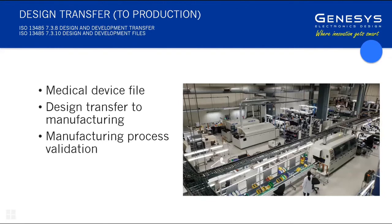So design transfer is really taking the outputs of the engineering, design and development work and establishing that in the production environment. What we see here is pick and place machines and the process for electronics assembly, but you can extrapolate this to any type of manufacturing or assembly environment. It is particularly important to consider that you have to validate the manufacturing process to show that it does what it's supposed to be doing. So this is distinct from validation of the design meeting a specification.